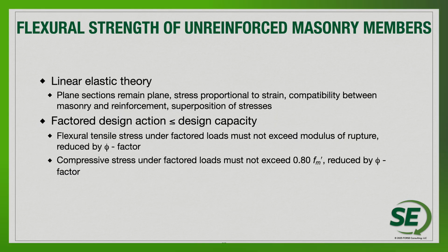Looking at the linear elastic theory, plane sections remain plane. Stress proportional to strain, compatibility between masonry and reinforcement, superposition of stresses. Really making sure that you also obviously have that good bond between the grout and the concrete masonry elements and the grout to the reinforcement to make sure that you have, again, that good compatibility within the section.